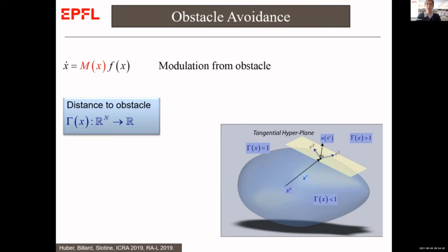Assume that you have this envelope, and that you have something even more than this envelope: it gives you a notion also of distance to the obstacle. Now we set that on the obstacle itself, the envelope is an isoline, which has a value, and we set this value to be 1. By default, if this envelope represents a distance, then away from the obstacle, this envelope is positive and keeps growing, and inside the obstacle, it's inferior to 1. So the envelope is exactly 1 around the obstacle, inferior to 1 inside, superior to 1 outside.